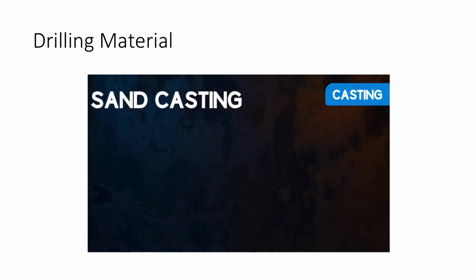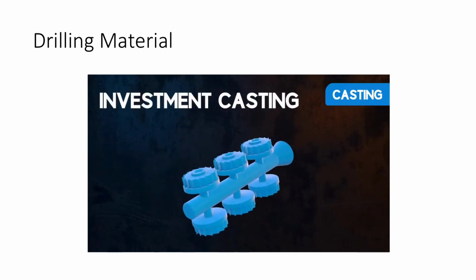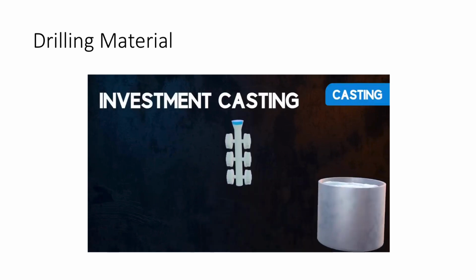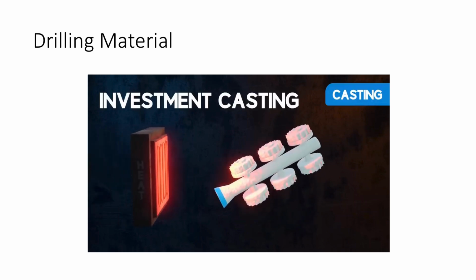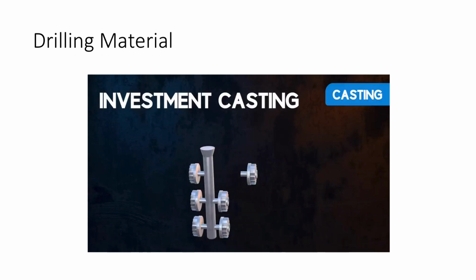The last casting process we will look at is investment casting. Several wax patterns of the same object are created and attached to a sprue. The wax tree is dipped into a slurry to create a ceramic mold. Heat is applied to melt out the wax. Molten metal is then poured into the ceramic mold. And once the casting has cooled, the mold is broken off.